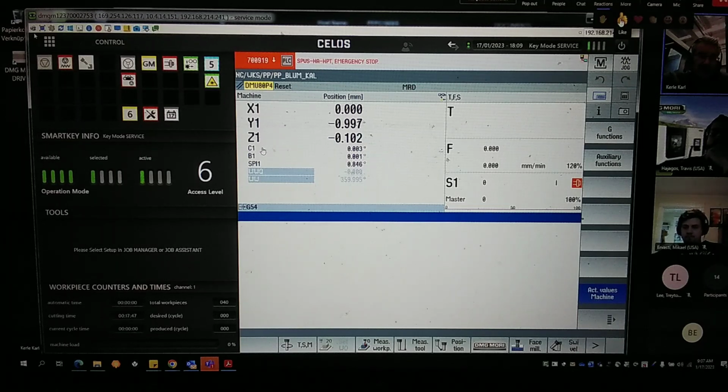Normally one channel is enough, but in that case, with a dual block, the maximum number of options could be assembled, and therefore, for the tool magazine and tool change system, we separate it into the second channel. Okay. When you think about it, a dual block could have 8 magazine discs.